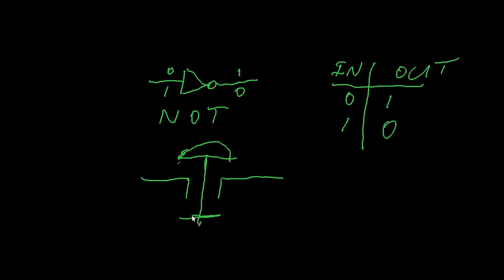And the shaft has this metal bar. What the metal bar does is it makes a connection between these two wires. Now there's a spring. What the spring does is the spring is pushing up on the push button. And of course you have your light bulb over here.